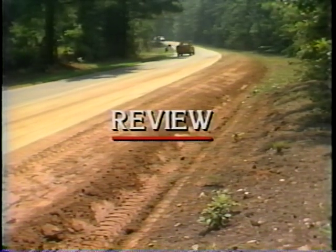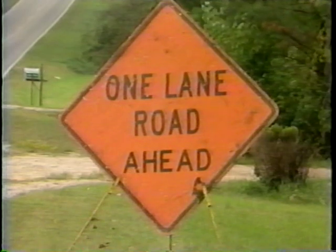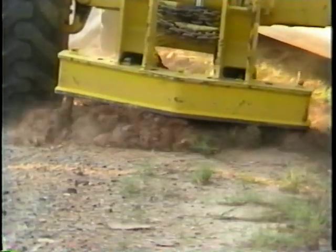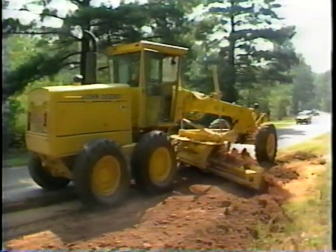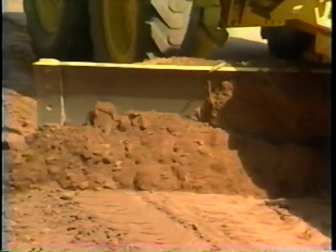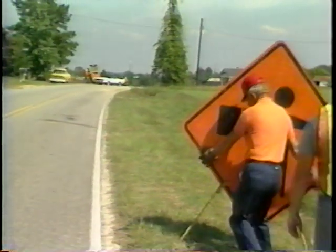Now, let us review the steps required for low shoulder repair. Number 1, place proper traffic control. Number 2, till or scarify existing shoulder material. Number 3, place material in low areas of shoulder. Number 4, spread material with grader to rough grade. Number 5, fine grade shoulder with motor grader. Number 6, compact shoulder. Number 7, remove traffic control.